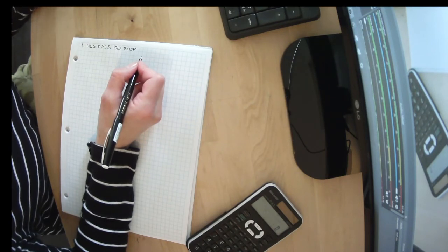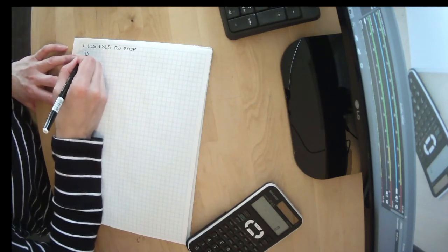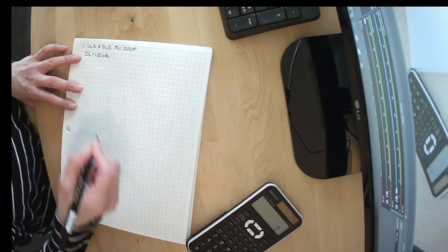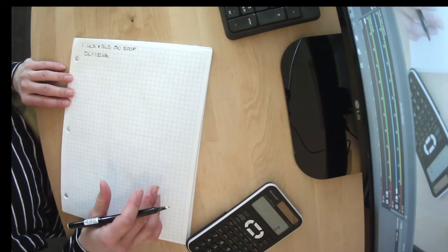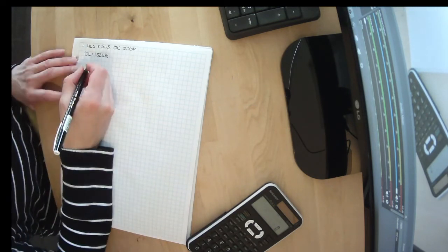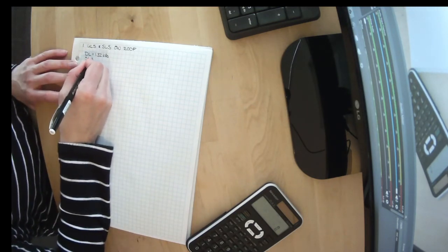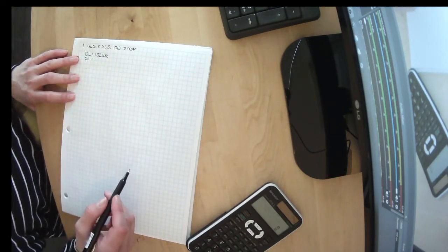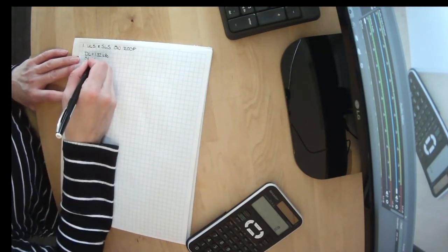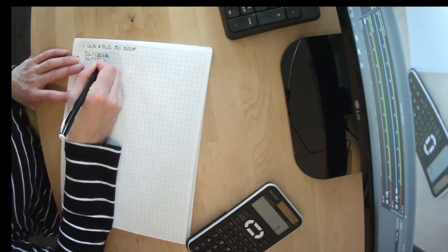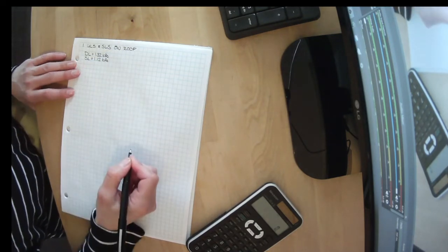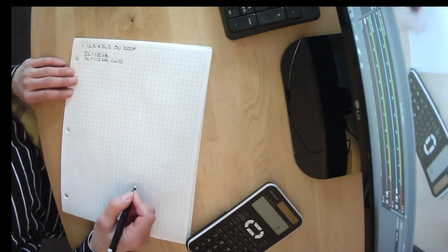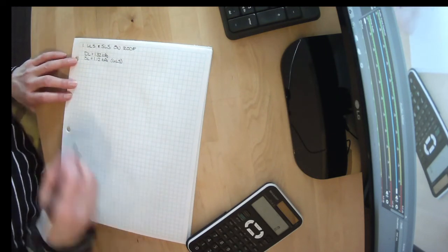Now, last week, we calculated that the roof had a dead load of 1.32 kPa. We looked at the roofing assembly and we calculated that ourselves. We looked at the snow load climatic data and calculated that our building had a snow load of 1.12 kPa for ULS values, or strength values.